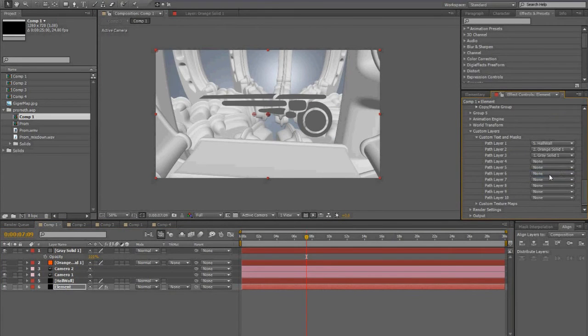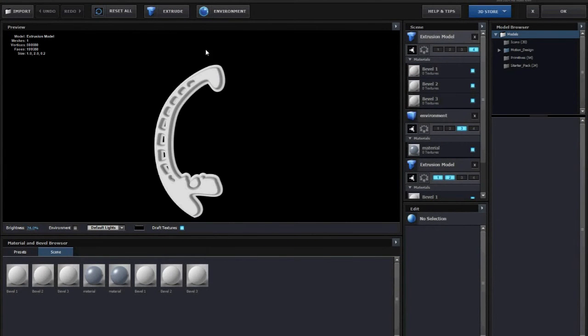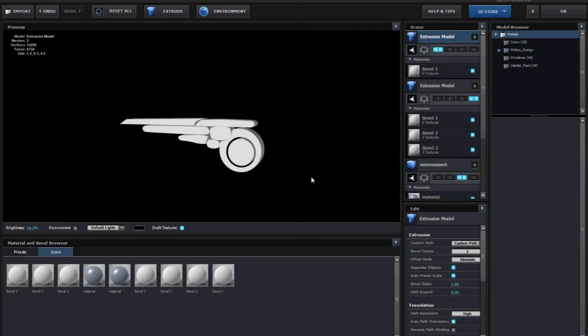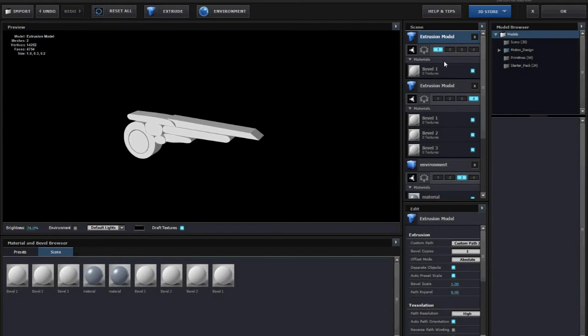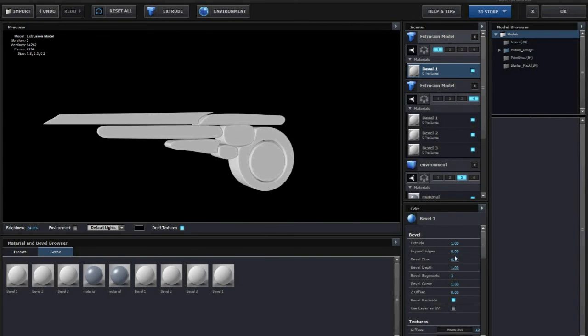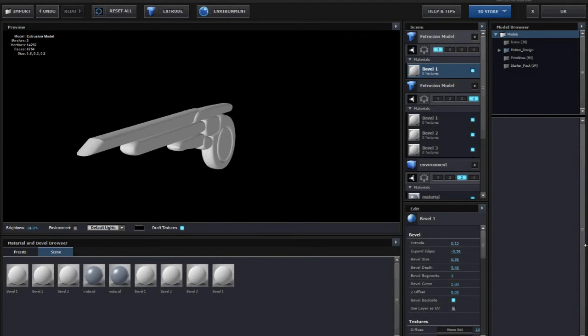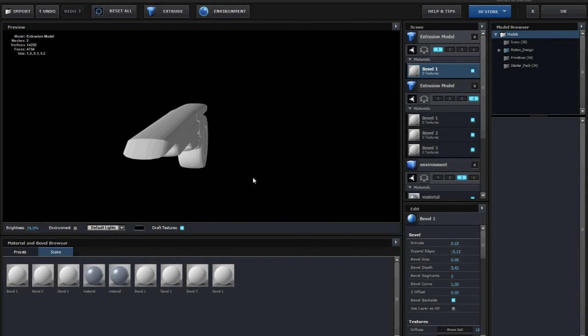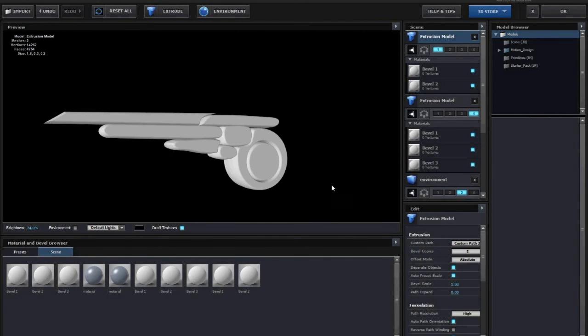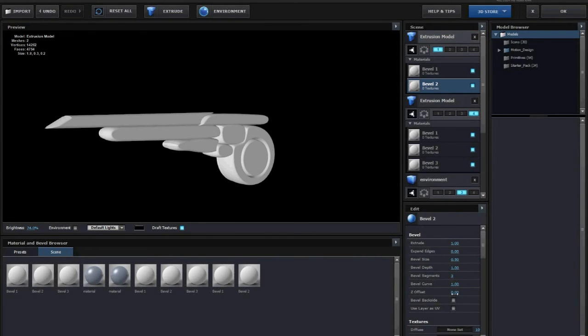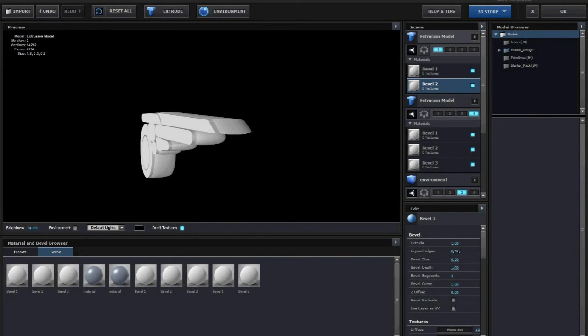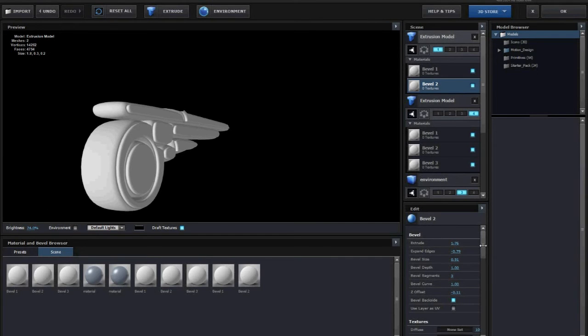So first off, just add this to the custom text and masks, and then go into elements. So you want to extrude the shape, select layer 3 or custom path 3, and with this it's just about getting a rounded kind of shape. Again, something very organic, suited to this look, very similar to what I did with the rib shape, but with a more rounded middle section, and then a cap on either end.